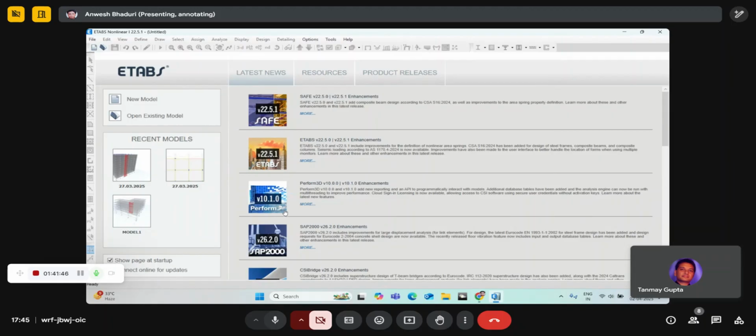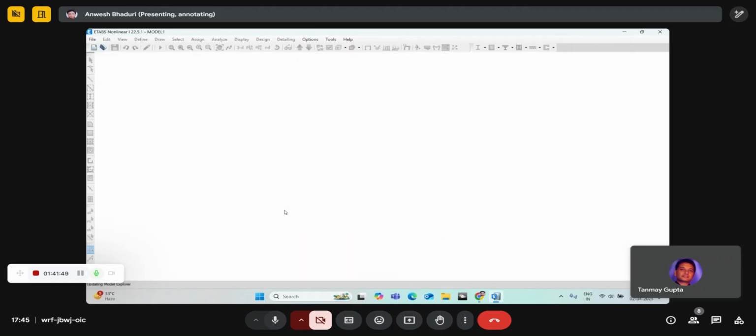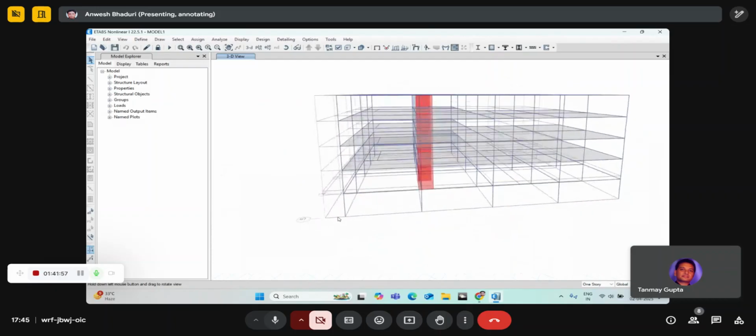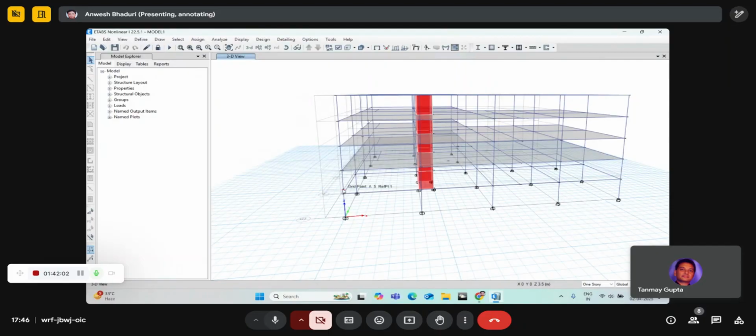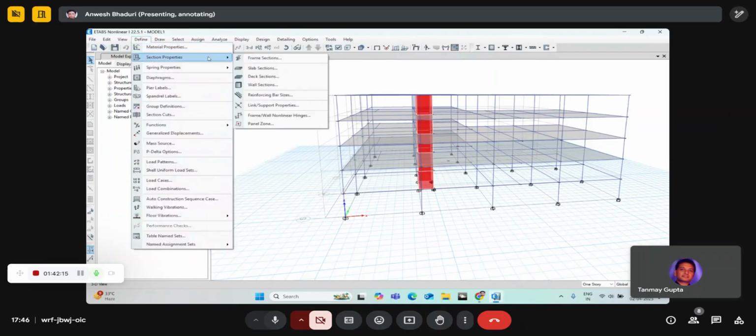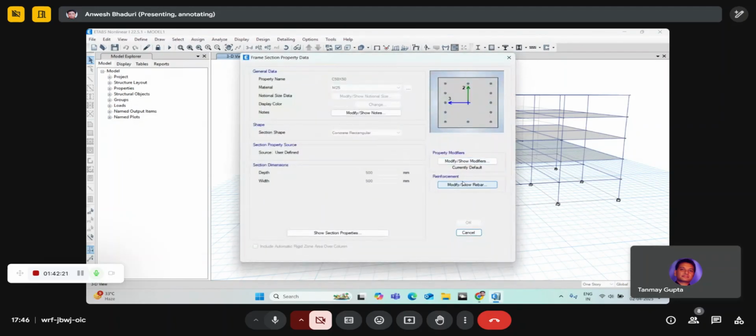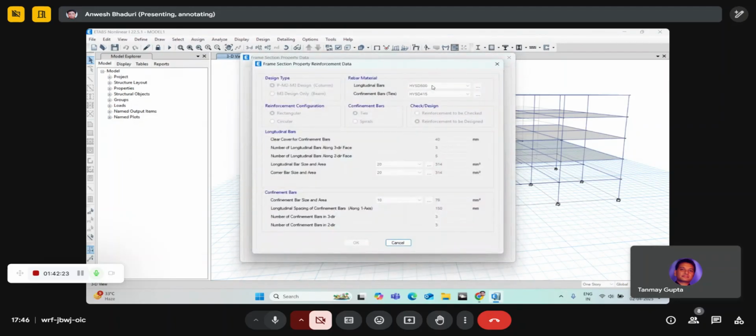We also need to give the reinforcement area for the beams and columns. For columns, it's automatically taking it, but that is only for generation of PMM curves. So whatever design values you get need to be separately defined in the column sections. These values have to be as per the design.